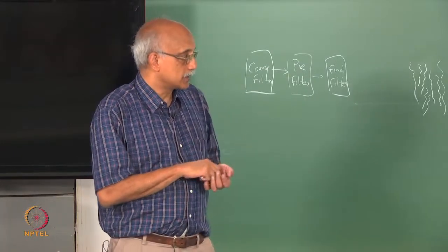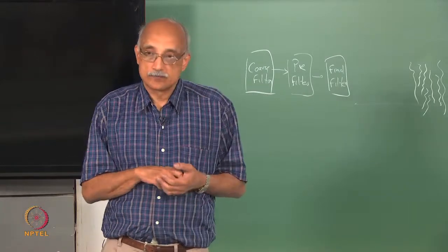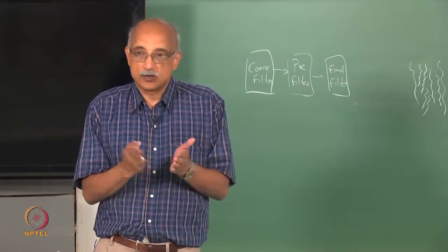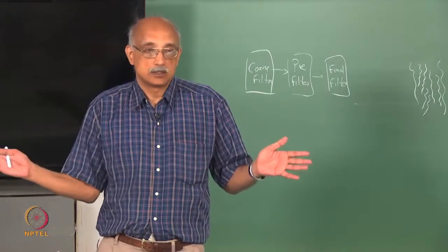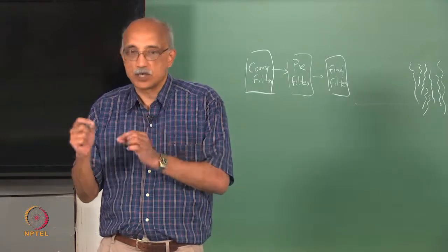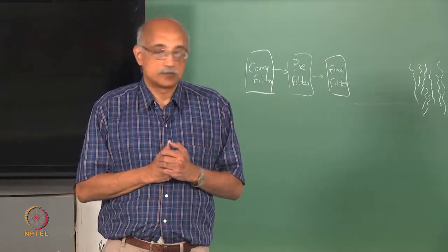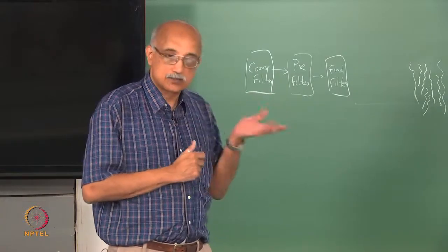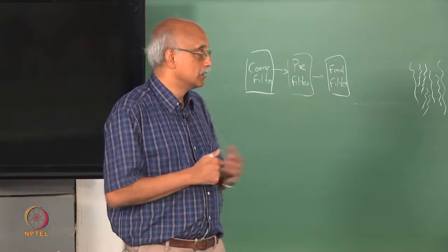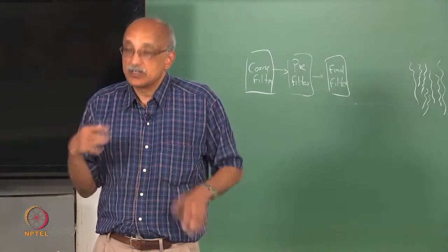The Gore-Tex filter is made of Teflon, and the way you make it is you take a film of Teflon and you keep stretching it until it just snaps at certain places and develops porosities. So, the Gore-Tex filter is not as well controlled and as uniform in the distribution and the size of the holes as a nuclear pore filter, but it is an even cleaner material.